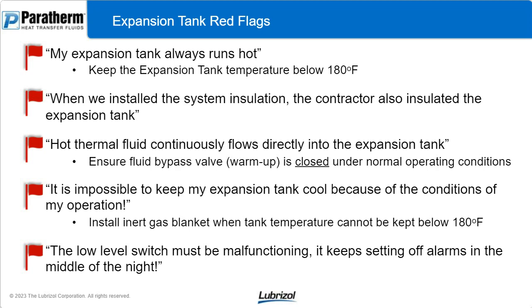If you're telling me that it's impossible to keep your tank cool, either because of the conditions of your operation, you're running at a very high temperature so the radiant heat's always going to be very high, or somebody plumbed in the expansion tank right above the heater stack and you can't control it. Under those situations, remember it takes heat plus fluid plus oxygen. If you can't remove the heat, obviously you can't remove the fluid. So if you can't remove the heat, then you have to displace the oxygen. Take that out of the equation. You can do that by displacing it with an inert gas blanket, usually nitrogen.